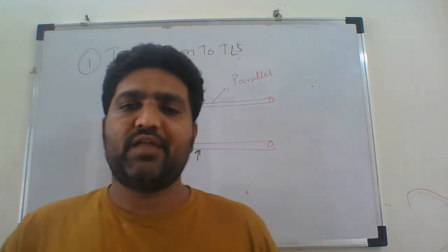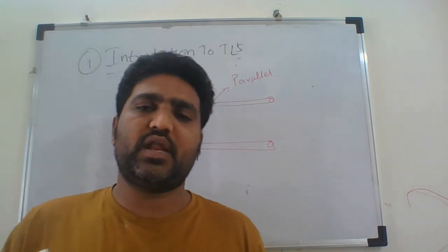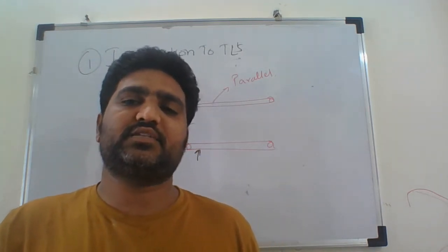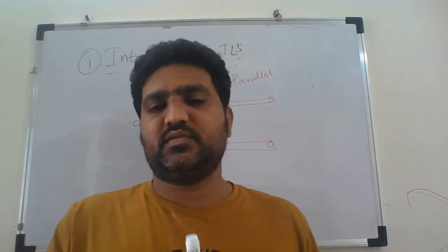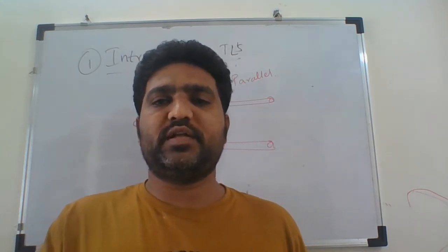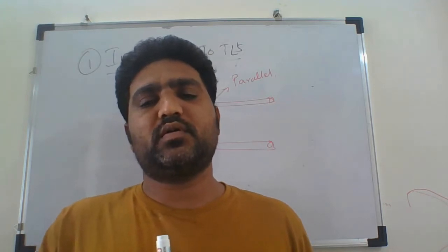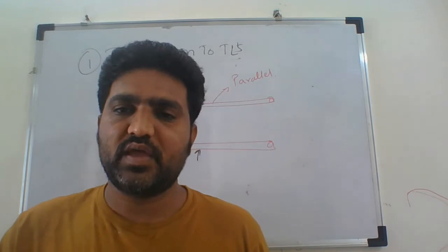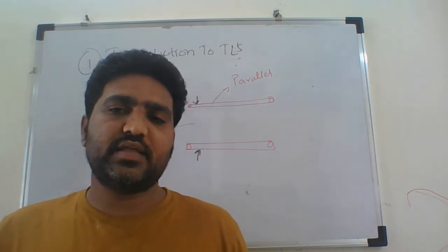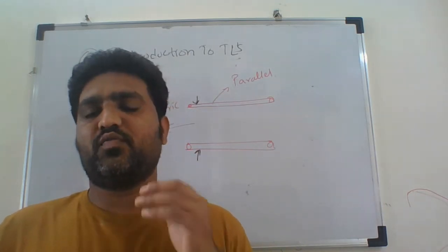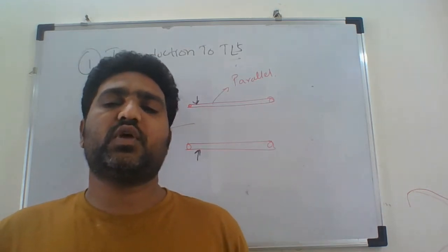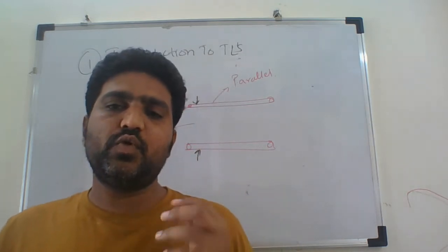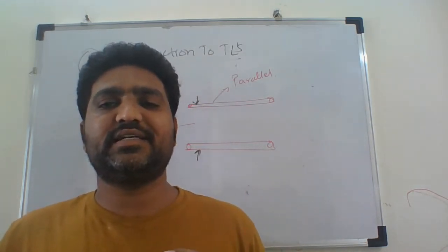First thing, can we call any pair of wires or conductors separated by a dielectric a transmission line? Yes, you can call it, but it is not required for us to deal with them as a transmission line. The transmission line theory, or field theory, comes into picture only when there is a transit time effect.